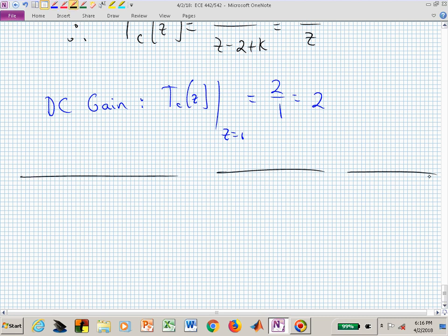That's what we want to start thinking about: what are the possibilities, what are our options for adjusting this one knob, just the proportional knob in a controller? Does that provide us with different possibilities? And in this case, it does. Is there a limiting value? Can we just keep cranking up the gain K and get better and better?